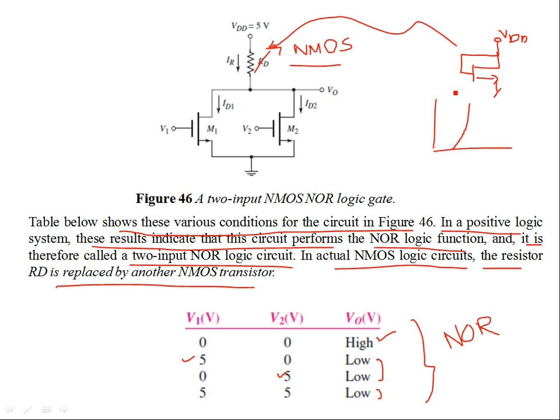So this is your VDS, and over here this is your ID. In this circuit configuration, your VG is basically equal to VD. That means if the transistor is to be an enhancement load device, the transistor operates in the saturation region.